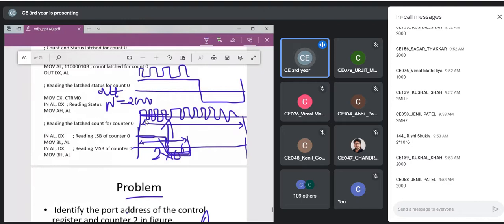Why? Because for 1000 clock pulses it will be high, and for the next 1000 it will be low. So I use 2000 clock pulses to make 1 pulse in the output. If I am having 2 mega pulses of clock in a second, how many output pulses will I have in this 1 second? It will be 1000.